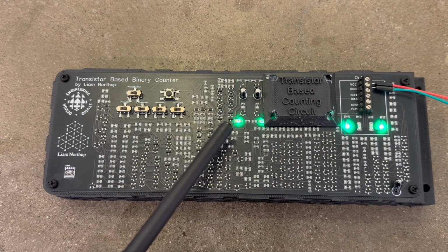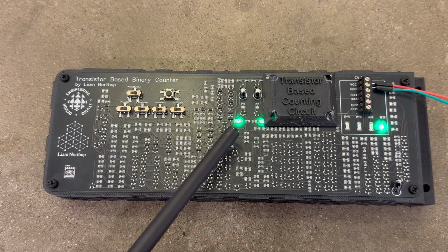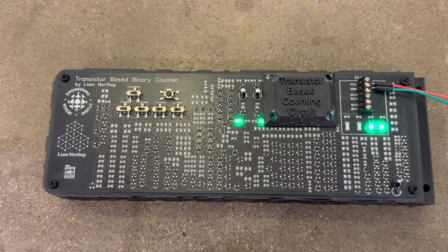It is also worth mentioning that my discrete astable multivibrator design seems to be messed up, so I had to replace the clock signal with an astable 555, which works because of a timing capacitor continuously charging and discharging between the internal 1/3 VCC and 2/3 VCC thresholds, causing the output to switch high and low in a repeating cycle. This configuration produced a steady square wave clock signal needed for my project.